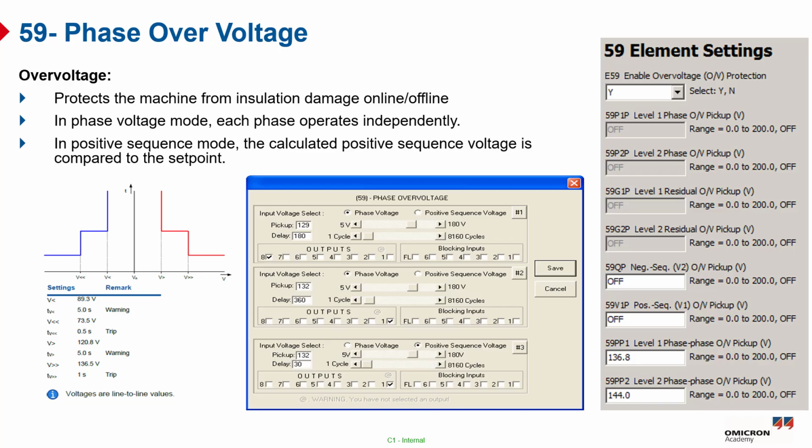protection, because an excessive overvoltage can result in a proportional increase in the frequency where the V over F protection doesn't operate. As explained in our example, the voltage protection function provides a two-stage under and over voltage protection. The undervoltage protection function is primarily intended as a protection for the connected loads, while on the other hand, the purpose of the overvoltage protection function is to avoid stator insulation defects inside the generators.